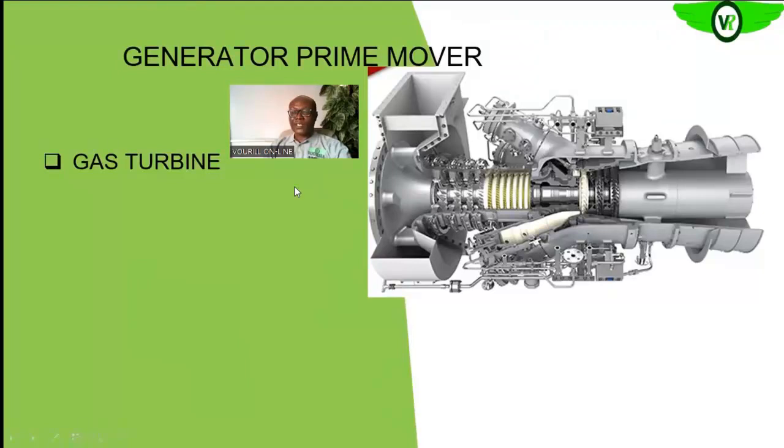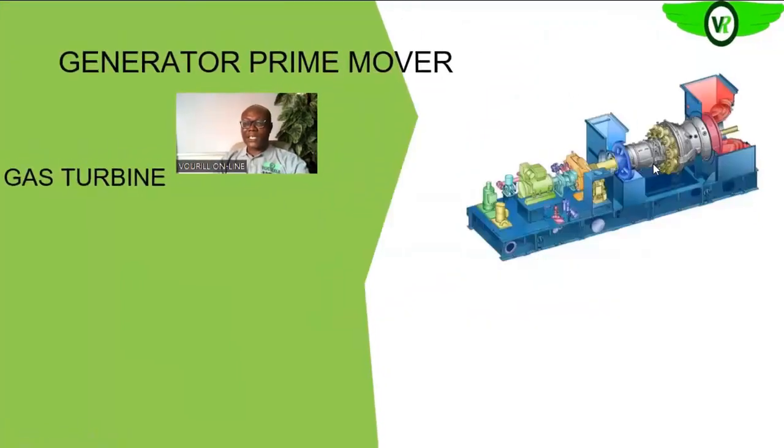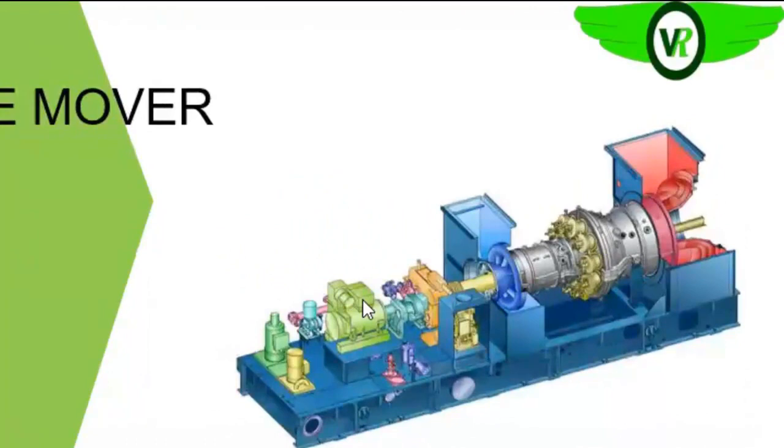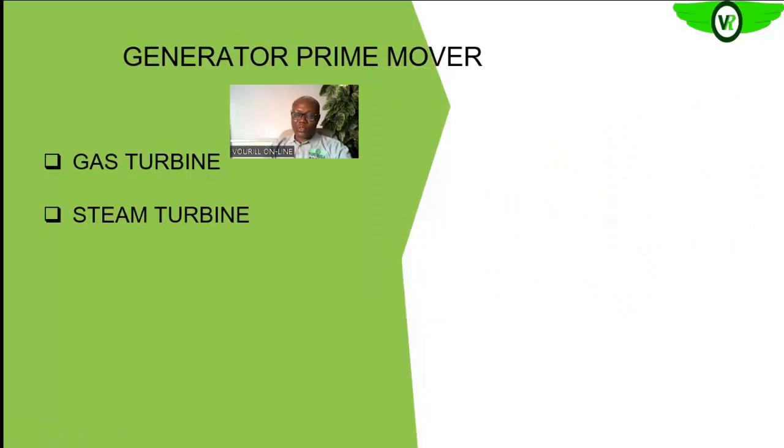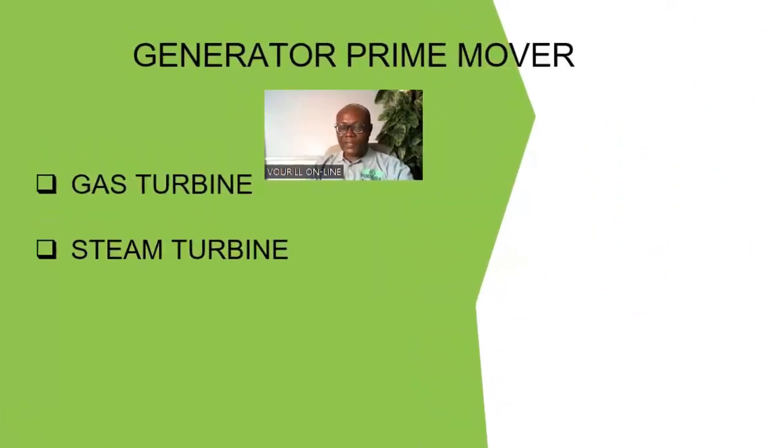So this shaft, as you saw in the earlier diagram, has the alternator attached to it by this gearbox. Since it is attached to the shaft and the chemical energy in the fuel has been converted into rotating mechanical energy, this alternator rotor will start to do what? To rotate, since it is coupled directly to this gearbox, which is in turn coupled to the shaft of the turbine.